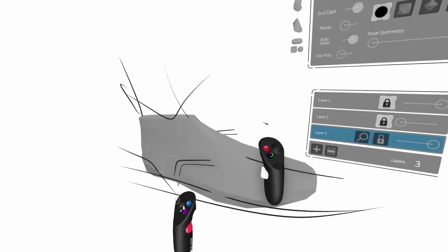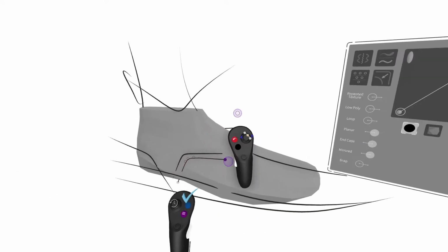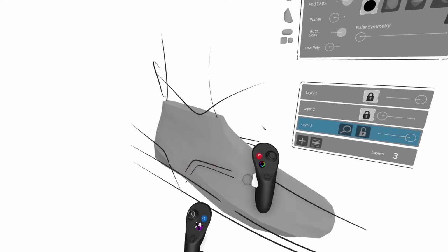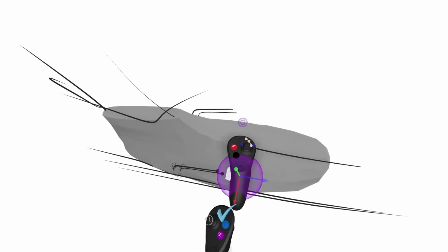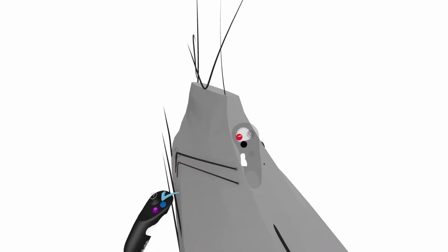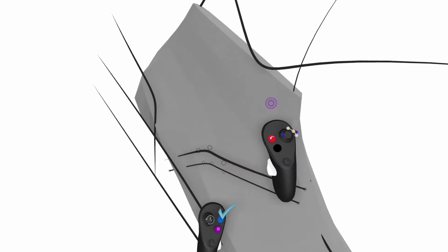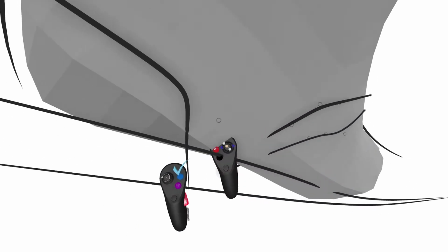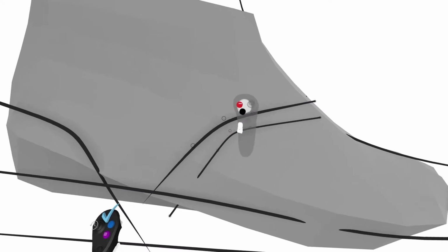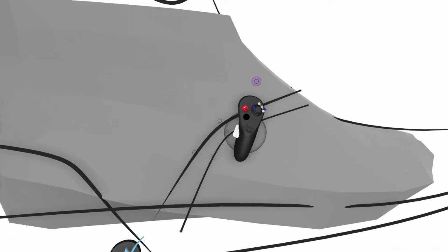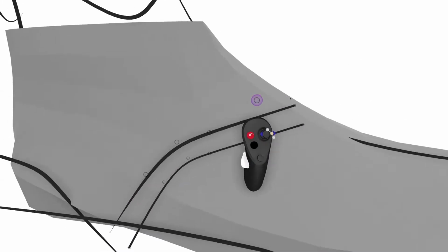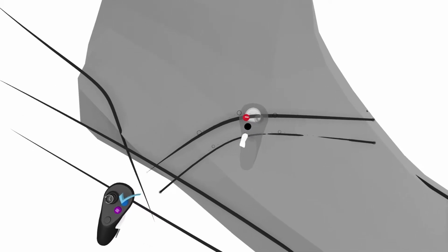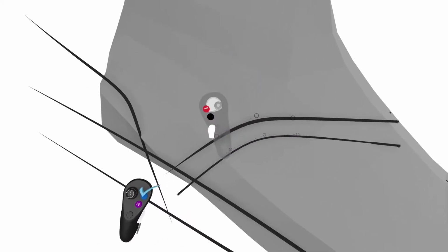And now that both of them are mirrored, I'm going to grab each one and also turn off the planar constraint. And what this is going to allow us to do is edit these guys as 3D splines. So we just moved from it being constrained to the plane that we defined to it being freeform. And I'm just going to move these close to the last and get it as tight and close as necessary. And you can just use the visual constraints to get that visual feedback, to get it to intersect and see where you want to define it.